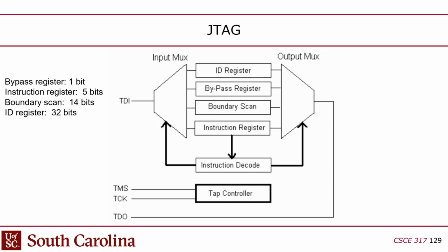And I think that, by the way, is probably why they don't use SPI for this. Now that I think about it, I never even thought about that, but with SPI it would be harder to have the daisy chain. Well, could you? No, because even with the daisy chain, it would be tough to work it out where you could put a different address in each device on the daisy chain. I guess you probably could do it somehow. But anyway, this is designed to be able to isolate specific devices on the chain, even though they all have the same TMS input. It seems like SPI was never designed to have multiple devices. Yeah, exactly.